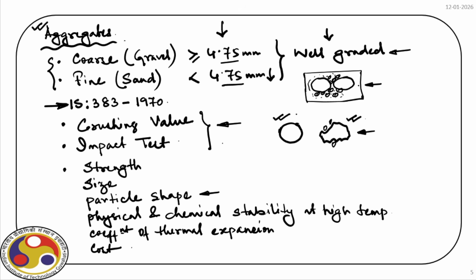Now, the final product is what we use in reinforced concrete, and the stability of this material at high temperature is also extremely important because we have different uses of cement concrete in the industry. In fact, for normal structures also, the temperature from winter to summer varies over a wider range, and obviously the thermal expansion of these materials should not be very high so that it can initiate cracking. That's why this property is so important.